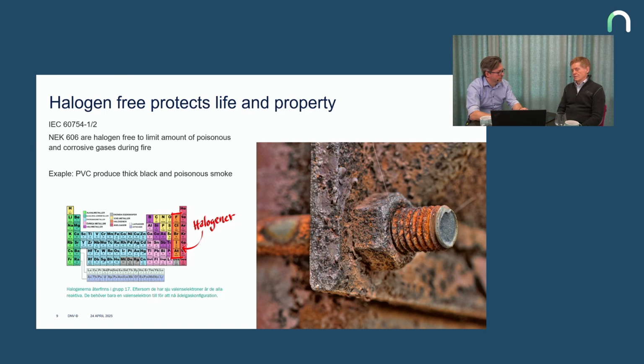But low smoke or halogen-free doesn't necessarily at the same time mean low smoke, does it? You can have a lot of smoke maybe, even if it's halogen-free? It's not one-to-one, but in many cases the materials will also comply with the low smoke test. Right, so it's both, but not necessarily. You cannot say it will be exactly the same, but in many cases this will go hand in hand. These requirements or these properties for materials.